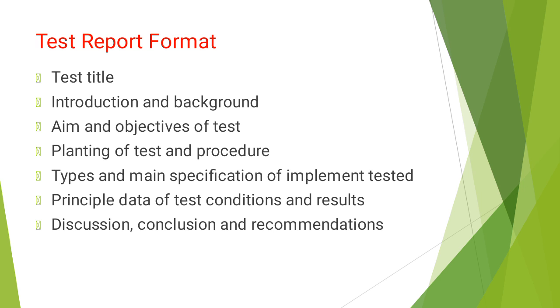Now the following is the test report format. It should contain the test title, and shall also contain the introduction and background. It also contains the aim and objective of the test, the planning of the test and procedure, the types and main specification of the implement tested, and the principal data of the test condition and result, and at last, discussion, conclusion and recommendation.